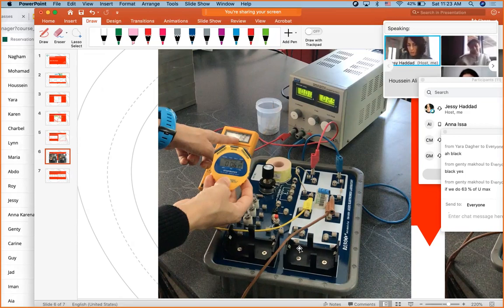So instead of using batteries, I used a regular power supply. The batteries are supposed to provide 1.5 volt, 1.5 volt in series 3 volts. I can read 3 volts all the time. Sometimes I have a fluctuation, 3 volts or 2.9, but trust me, this is constant. It's gonna stay 2.9 throughout my experiment. Now my voltmeter, this is a screenshot from the video. So in the video you will see the voltmeter is connected to the capacitor only. And this is the stopwatch I'm using. You can have a look. This is 6.19 seconds. Just for you to have an idea, digital uncertainty, think about it.